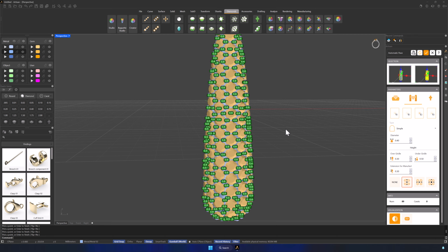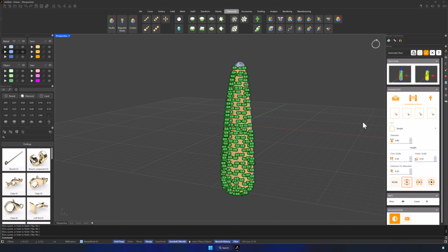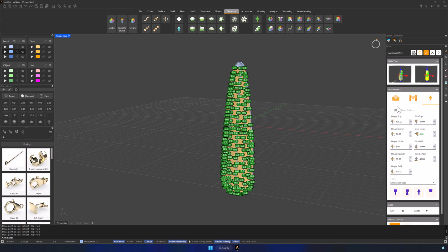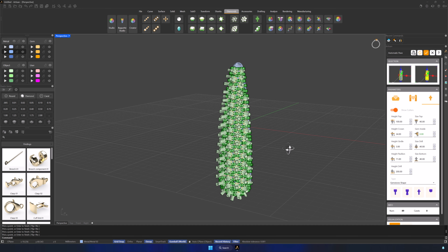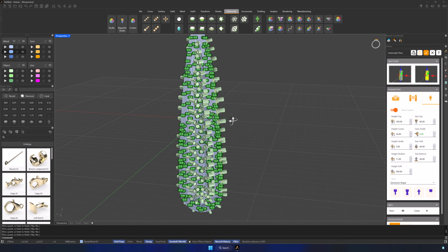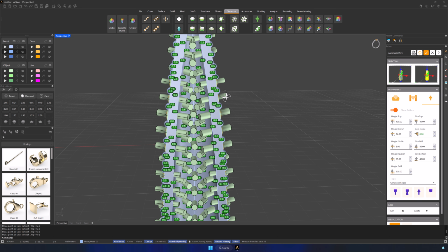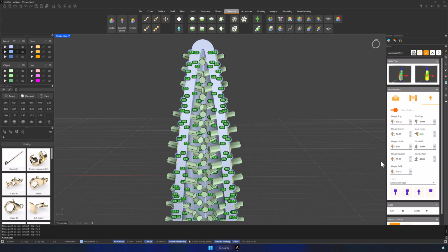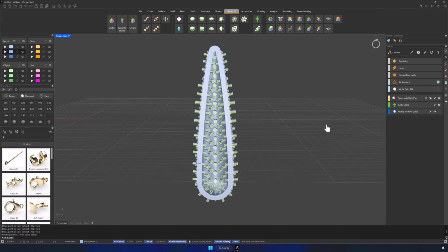Once you finish editing the prongs, press right-click to finish. Open the Cutters tab and activate the cutters. In the inner part of the model, overlapping cutters may be visible. To fix this, reduce the height drill to 175 mm and click Update, then accept the command.